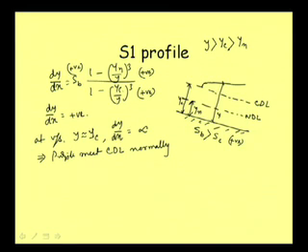So, the shape of the profile at the upstream end will not continuously extend to a far distance this way, and rather it will be just rising from the critical depth line in this way.